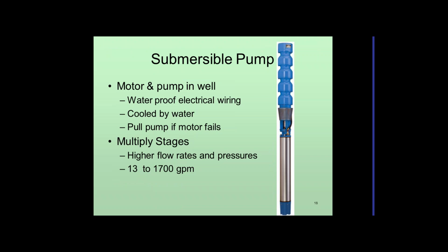The other type of pump we can use is a submersible pump. On the right here we've got a picture. The silver part is the motor. The nice part about a submersible is that the motor is water cooled in this case. We've got an electric line running in here. This is our inlet screen.